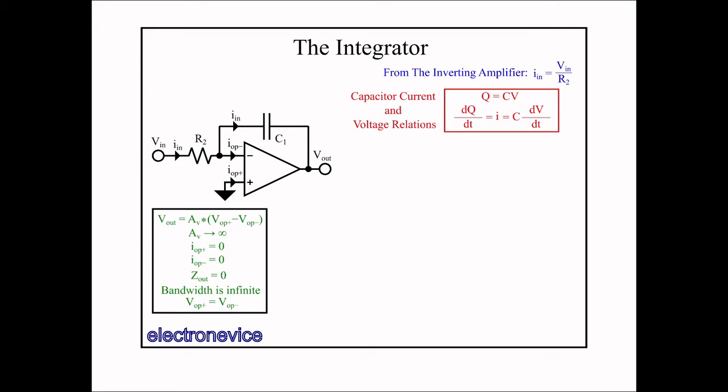In other words, for Vin signals that change more slowly, we will tend to produce very high voltages across the capacitor, because the capacitor will look more like an open circuit to In. And for Vin signals that change more quickly, In will tend to see the capacitor more as a short circuit, and so the voltage drop across it will tend to be small. Thus, slower signals will tend to be amplified more than faster signals.